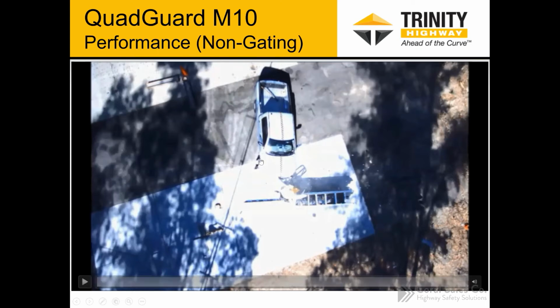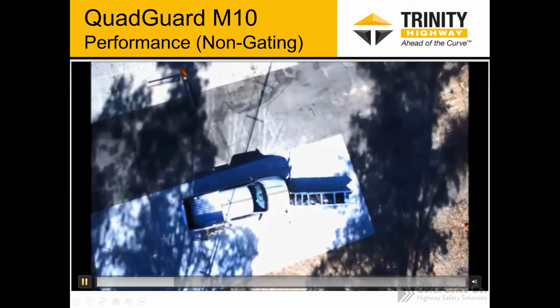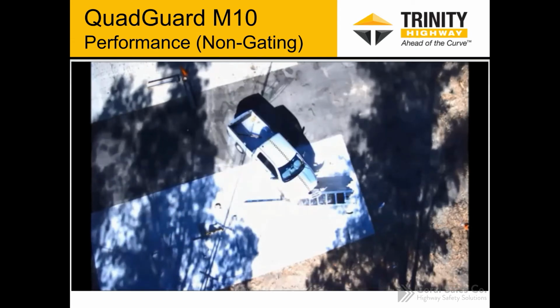There's no rolling of the vehicle, and there's even a maximum pitch angle that it can rotate up to where the MASH criteria allows it to be considered successful. So you can kind of see in this, normally it might go right through that, but with a crash cushion, it's going to catch the vehicle and bring it to a controlled stop.